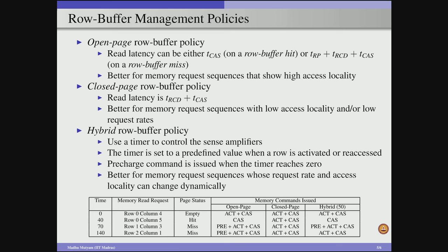But to implement the hybrid based policy, we require extra hardware in terms of the timers and incrementing the timers and resetting these timers and so on. But those things are not there with open page and the closed page policies.